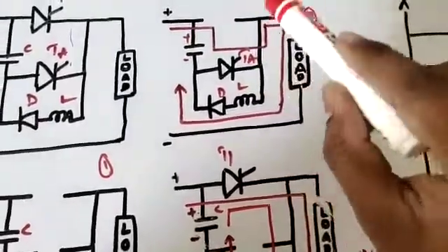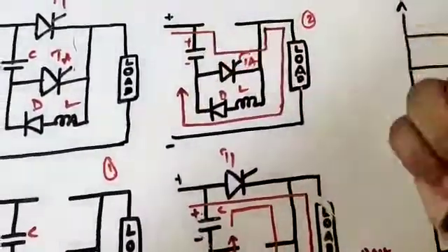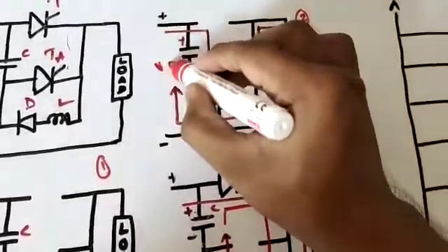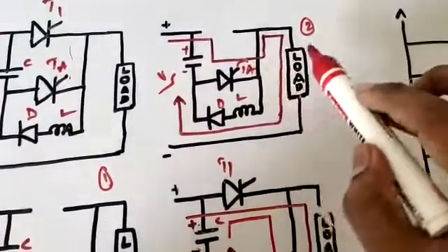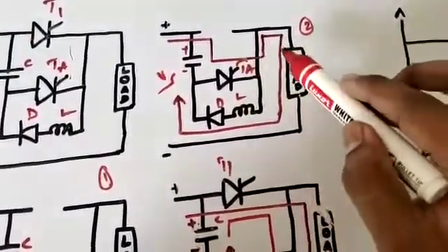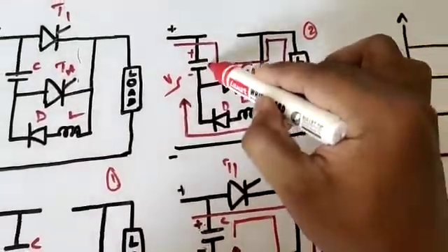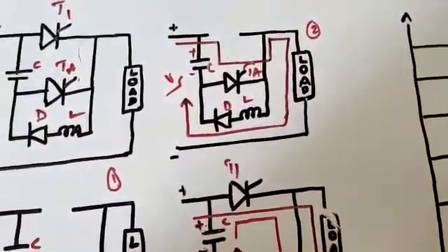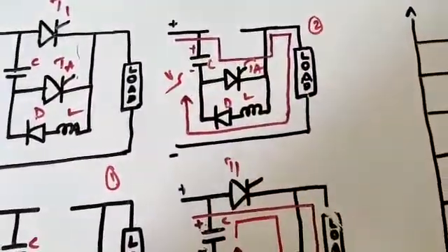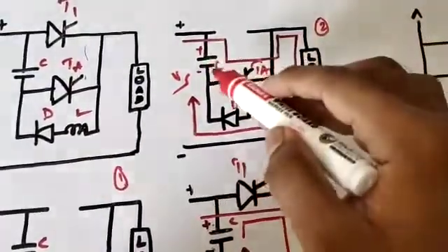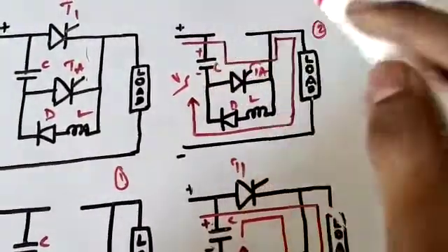So the flow of current should be as shown in the figure. This is the way the current flows. This is Vs. The capacitor will charge due to the loop current flowing in this circuit. We have the polarities of the capacitor like this. So what is the voltage across this capacitor right now? It is the supply voltage, because it is going to charge up to the supply voltage.